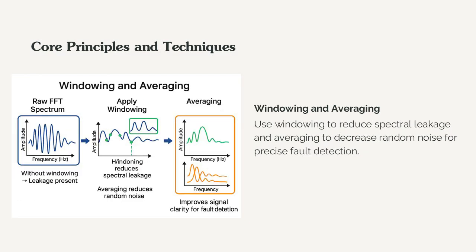Additionally, windowing techniques are applied to minimize spectral leakage, and averaging methods help reduce random noise. These concepts form the backbone of vibration analysis, enabling precise interpretation of machine health and facilitating predictive maintenance strategies.